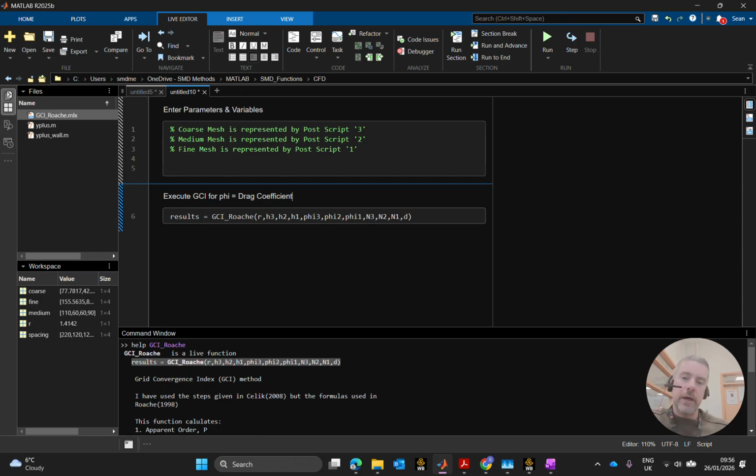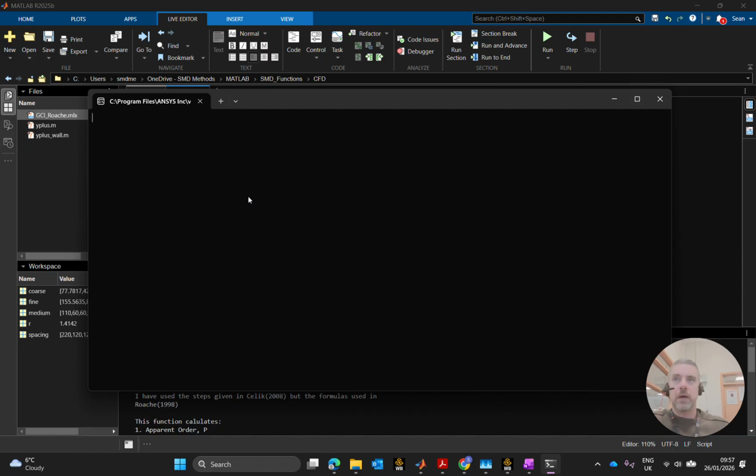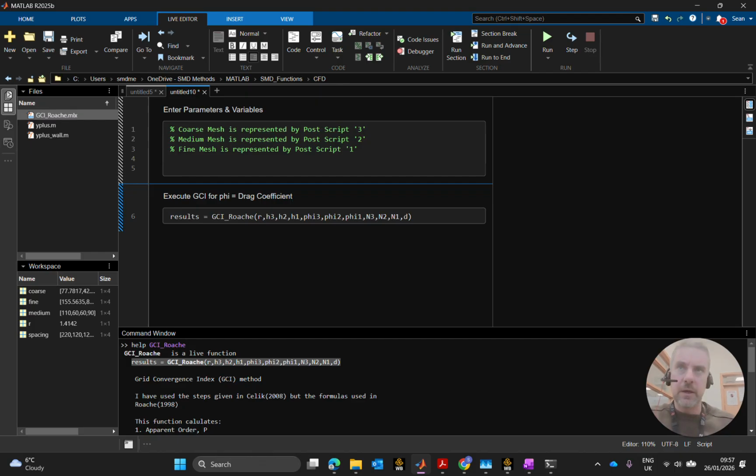Obviously on a steady state analysis, you get a calculation of pressure and velocity at each grid centroid, at the middle of each grid, and then we start with an initialization and obviously a very bad estimation of what they are till we get to the final one. But the final one there is based on our calculations being completed at a certain time. That's what I really meant by that.